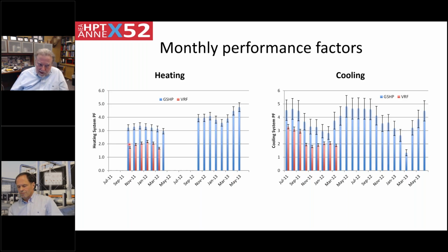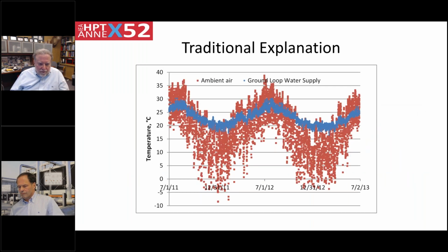So that was interesting. But another interesting thing, which we'll come back to, is if you look at the first season of operation, the ground source heat pump had about a 3 performance factor, and the second season had about a factor of 4. Right? There's a large jump. So we'll come back to that in a minute. For cooling, generally the ground source heat pump system performs better, but not necessarily as dramatically better. So the traditional